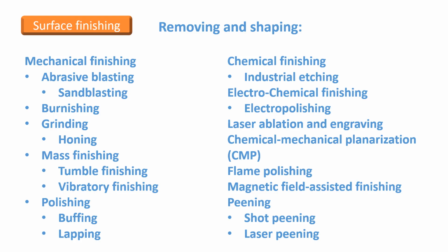The most common mechanical surface treatment methods are sandblasting and grinding, and the most common mass finishing methods are drum polishing and vibratory polishing. Peening and its various variations are also very common methods. In these processes, the surface of the metal is modified to improve its material properties. Local modification on the surface of the metal is intended to cause compressive stresses, which also reduce any tensile stresses on the surface. Peening also shapes the metal surface. When peening shapes the surface and also changes the material properties, then it actually belongs to both groups.